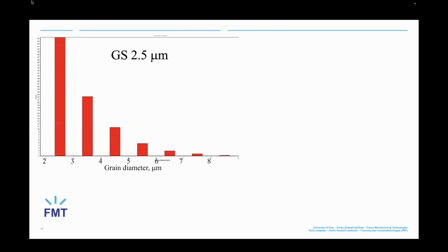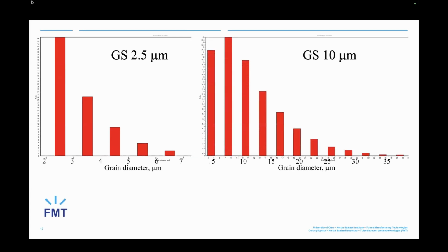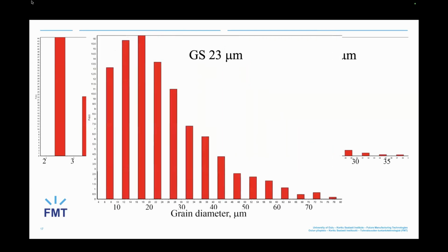Okay, coming to the grain size distribution, which we calculated for 1000. We found the grain size is almost 2.5 microns for full recrystallization, at 1100 almost 10 microns, and at 1200 about 23 microns. This is flash annealing for full recrystallization, with equiaxed grains but coarsening at 1200.